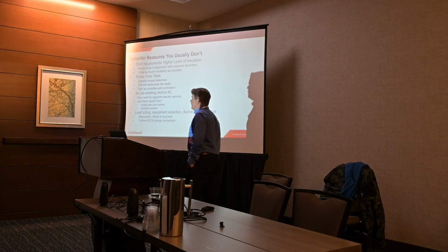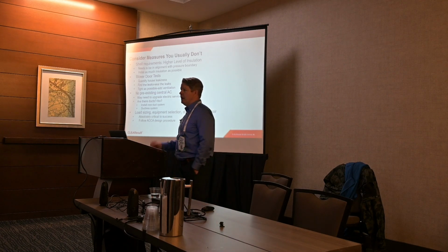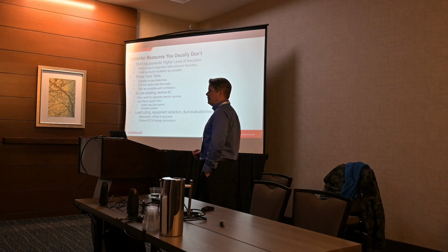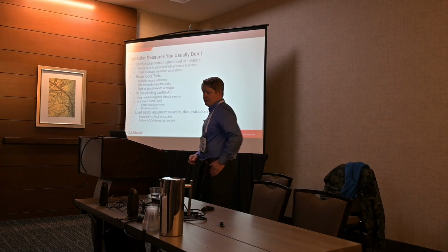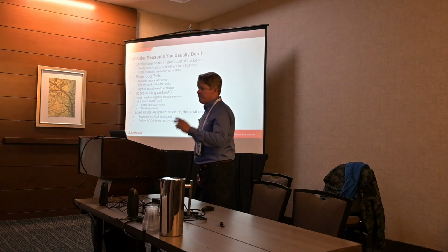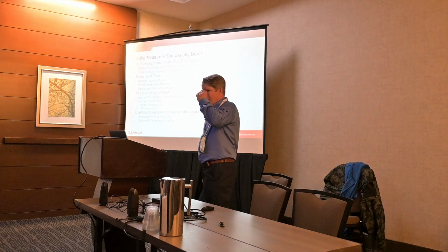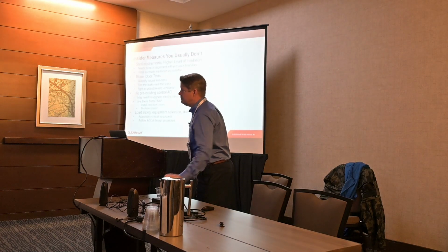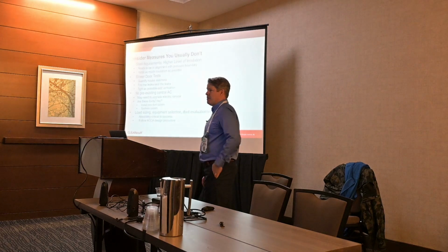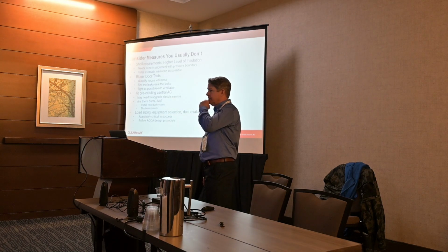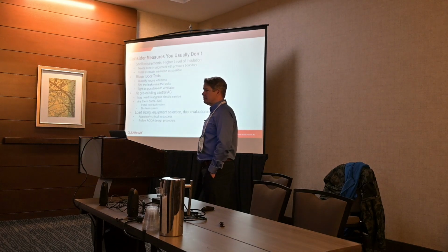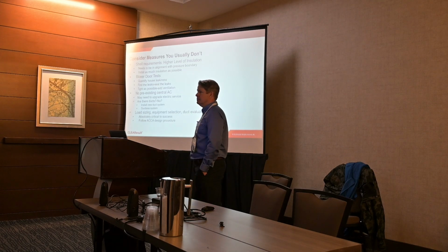You don't see that much, right? No, I haven't seen it at all yet, but I think they're really starting to perfect the air to water, and you may start seeing it soon. The big problem currently is they can't get the temperature rise. Right. They're talking with the new refrigerants possibly being able to do it. One of the big things is, if a person's got a boiler system, that boiler system is not sized for cold water temperatures. And so you have an air to water that might put out 120, 140, but if the system is designed to run at 180 degrees water, that will never supply. Well, yeah, you have to replace the boiler baseboard.